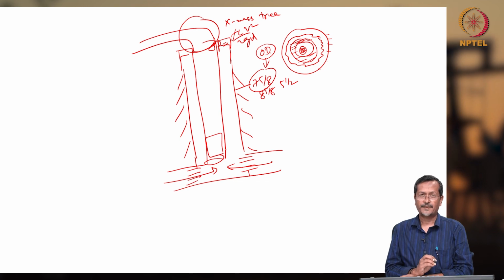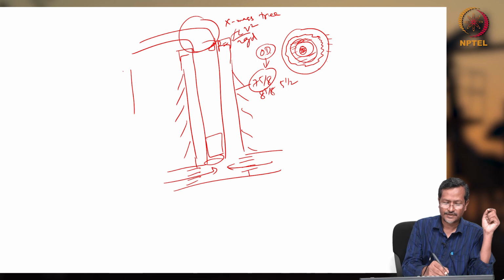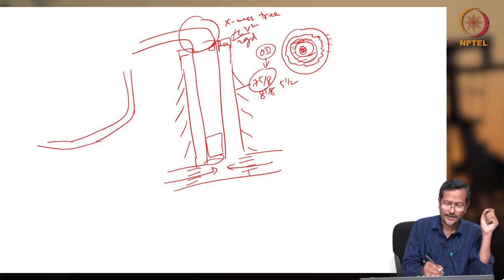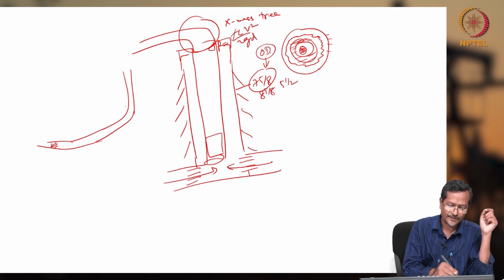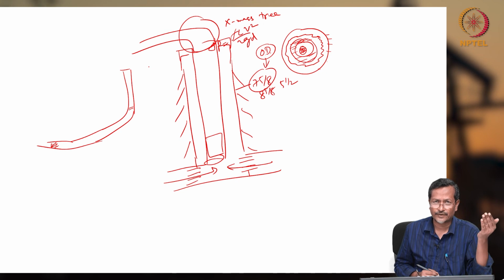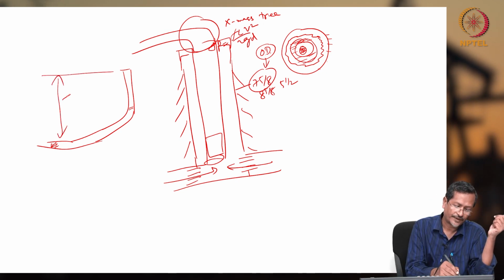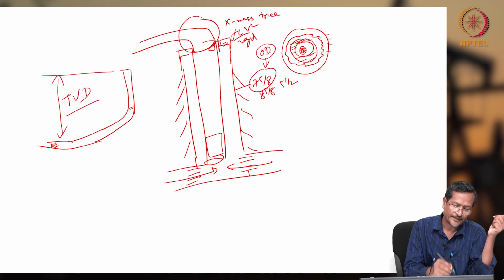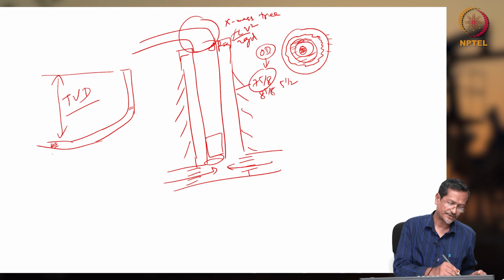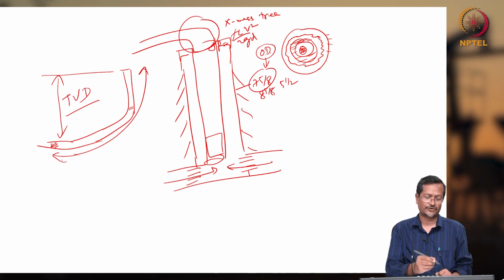Okay, and pump can be installed in vertical or horizontal condition. For example, you have one horizontal wellbore, it is going like this. So you can install pump here or you can install here based on your head. And whenever you are calculating your hydrostatic head, you have to calculate true vertical depth, actual vertical depth. And what will be your frictional pressure drop? Frictional pressure drop means you have to calculate this length. Okay, this will be giving your frictional pressure drop.